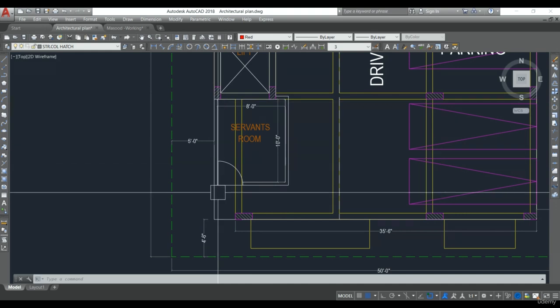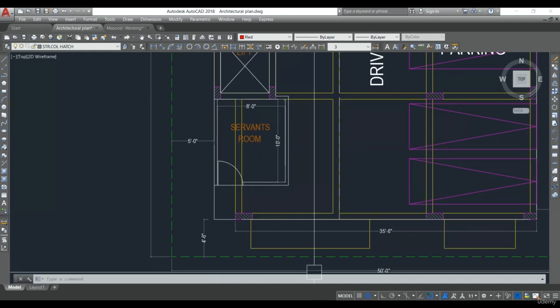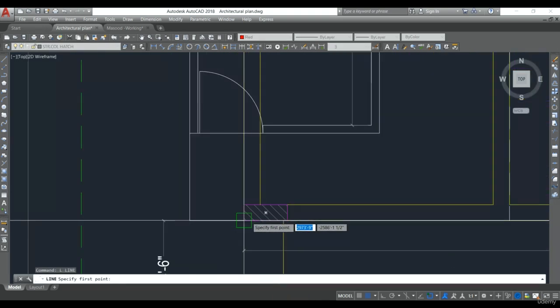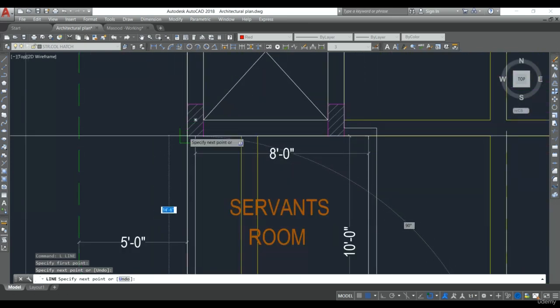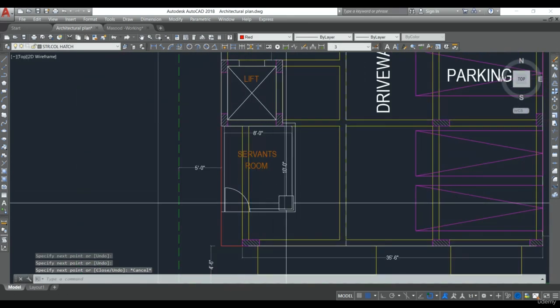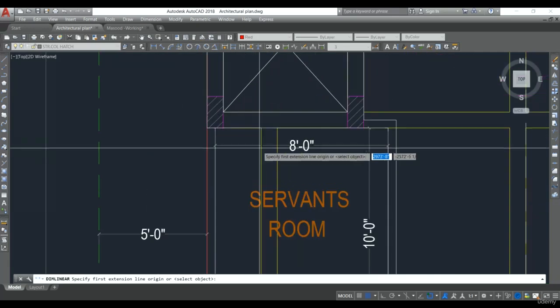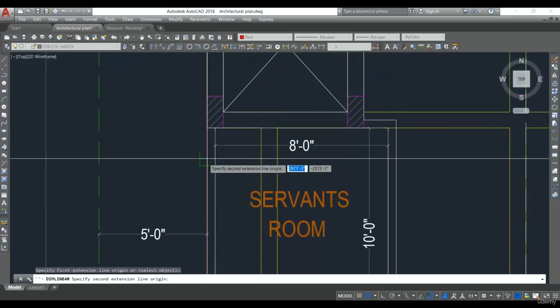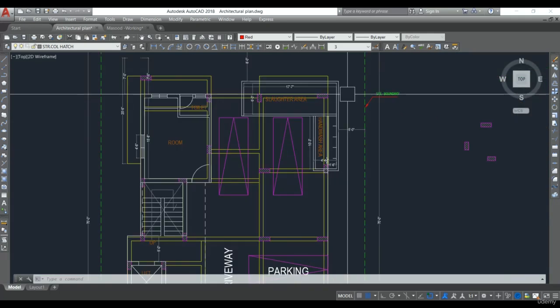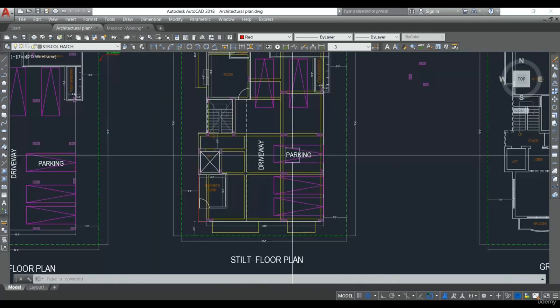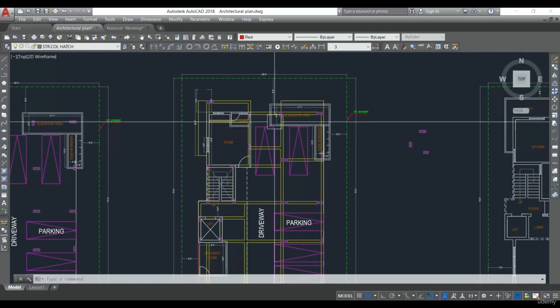So to make that roof, we have to make a cantilever portion here. So let me take the slab from here only. The line is given here. So till here we need to make a cantilever. From this beam, it is around 2 feet 6 inches cantilever slab. Rest everything is fine because it is a total parking area only.